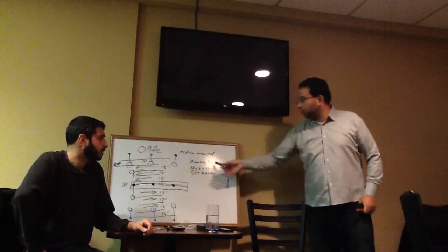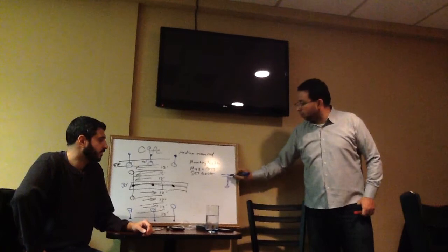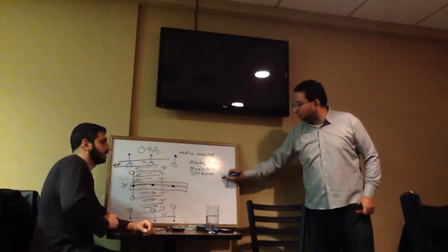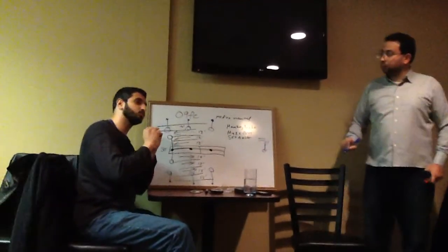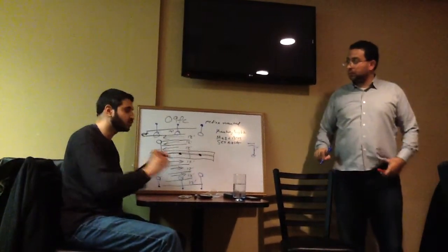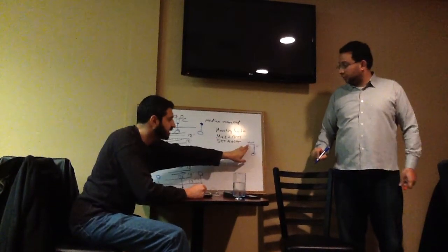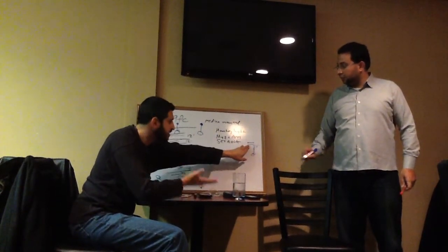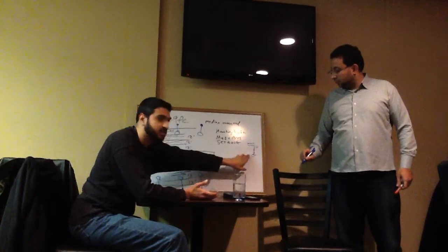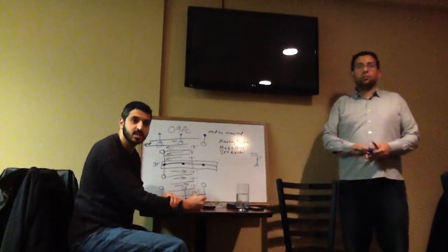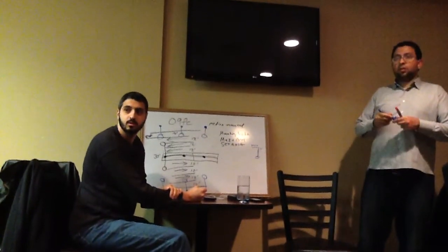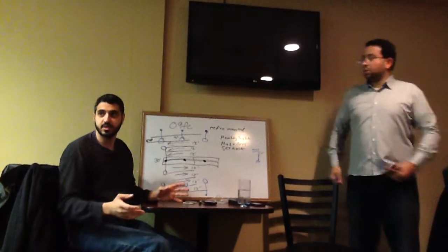When you say mounting height, I'm assuming he wants all the way from this point. It'll be mounting height, because that's what you put into the software to do the analysis. What's considered mounting height is wherever the lamp is, the bottom of that lamp, to the top of the sidewalk or pavement, whatever area you like, like he showed, all the way to the ground. If we were doing an office space with a table in front of you, it wouldn't be to the ground, because the people are looking at the desks, so it'll be to the table.